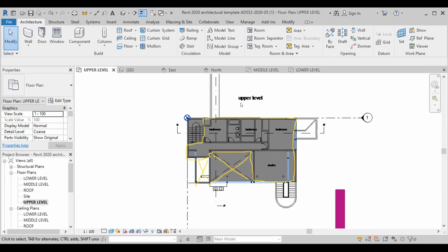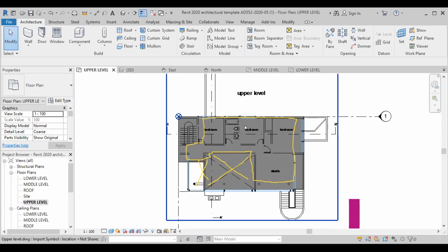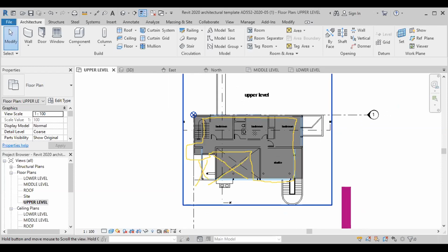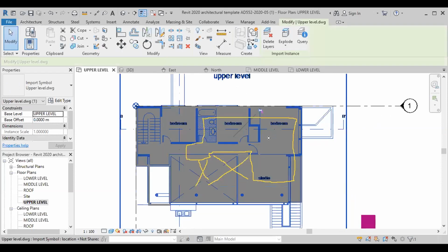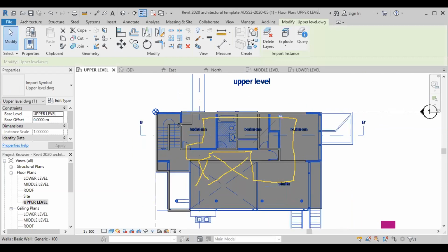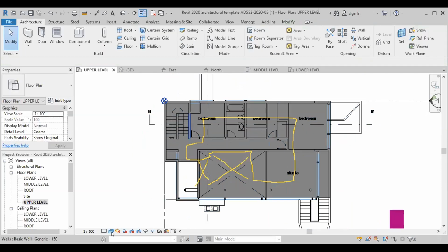Okay. So what you have to do now is modify the boundary of this floor. So how to modify the boundary? You have to select the floor first. Now, in order to make things selectable from the surface, you just activate this one.